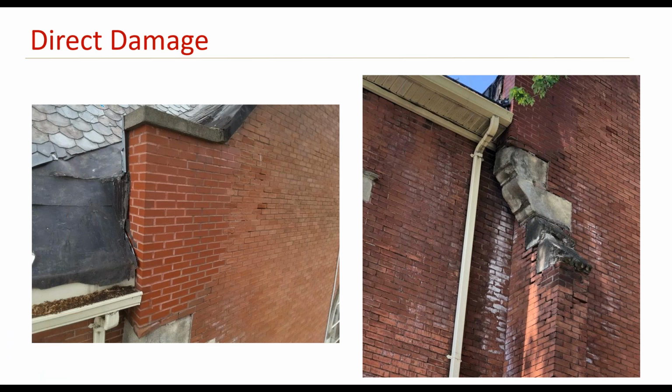Instead of the water going with the slope and then moving this way and then to the rain gutter, we start having water overflow over this parapet here. Also, we do have the flashing here, and the sealants are damaged. And another failure here is the accumulation of the tree leaves and bits of branches that block the rain gutter. And now you see all these are sources of, or these are failures to the building envelope.